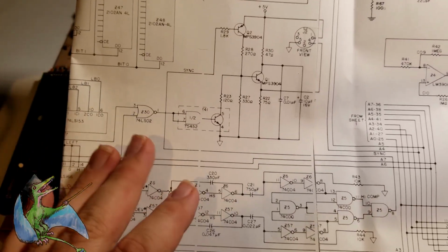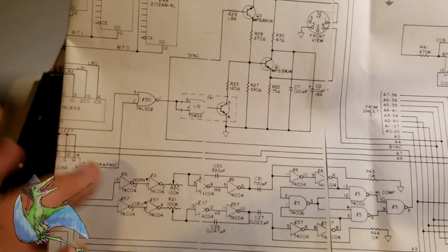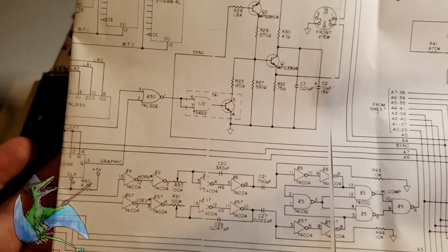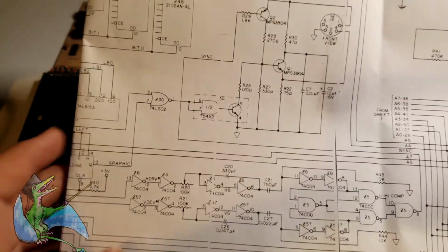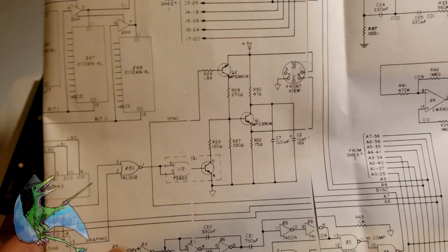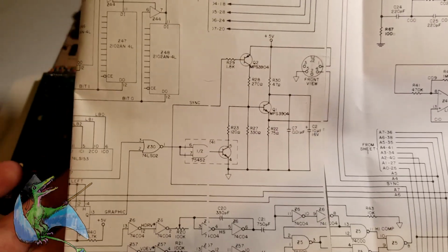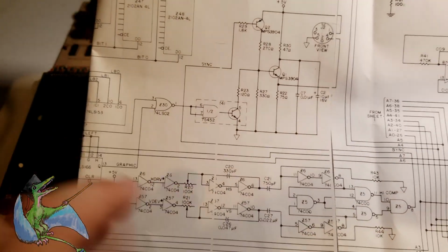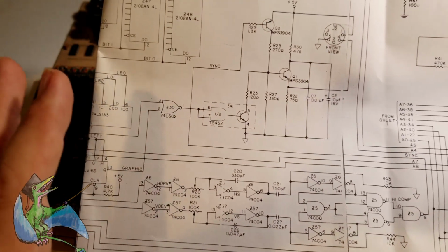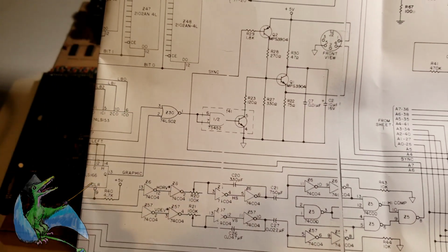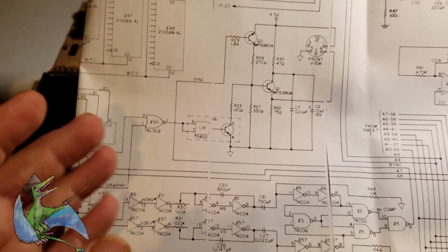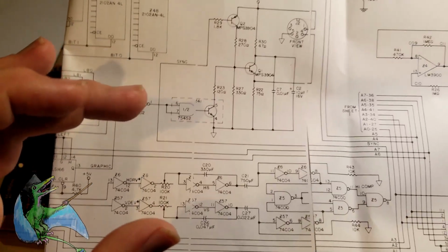The CMOS tends to run much closer to the rails, and it uses less power. It's better, except back in the 70s it was quite a lot slower than TTL. So the TRS-80 specifically used CMOS in this section because they wanted to clean up this pulse, make it sharper, and have a bigger swing between 0 and 1.